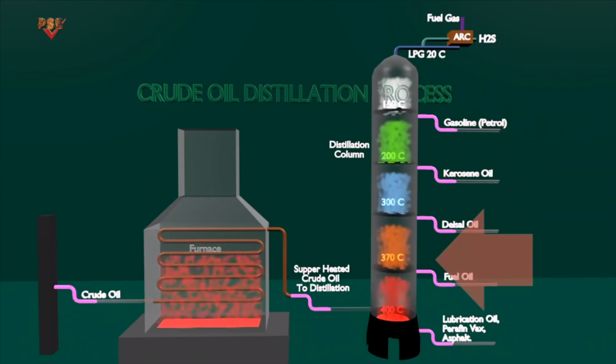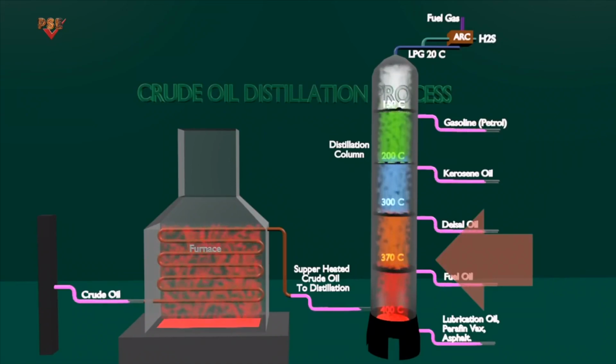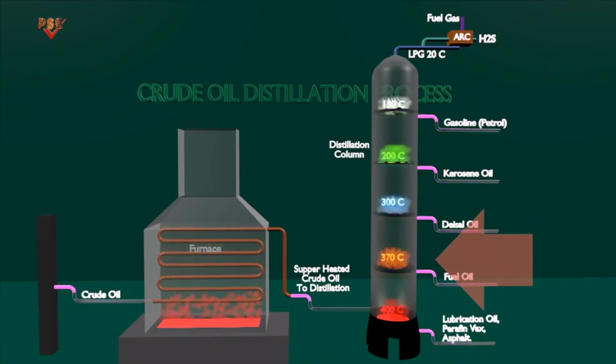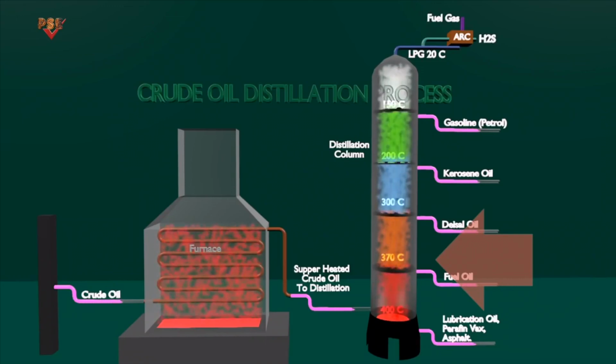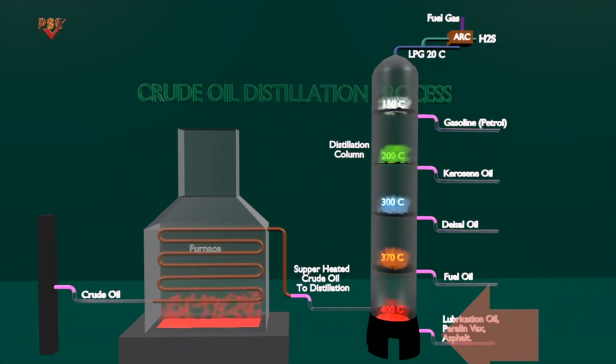Heavier distillate streams are also treated and blended into finished diesel fuel or home heating oil, or are further processed in conversion units such as fluidized catalytic cracking and hydrocracking. The routing of these streams will vary as product demand changes to either maximize diesel production or gasoline production. The lowest end of the column gives asphalt, power generation and marine fuel.